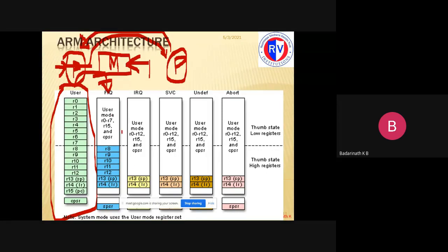The names are the same, but physically they are different, so you are not disturbing the original one. The names should be the same because the programmer cannot think differently when writing different programs for sensors or for general purpose. For a programmer, always R0 to R15 is available for writing the program. Whether physically you provide another copy or the same copy does not matter.